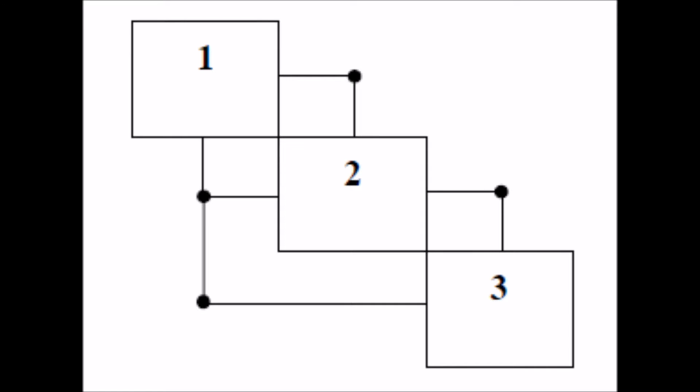Subsystem 2 then utilizes the cathode to heat the gas and prep the propellant for subsystem 3. The nozzle then utilizes the thermal capabilities from the discharge chamber and induces thrust out of the system. This thrust is also monitored by subsystem 1 with the assumption that a certain thrust capability is wished to be sustained. Any increase or decrease in flow rate through the nozzle from the chamber has a direct impact on thrust output.